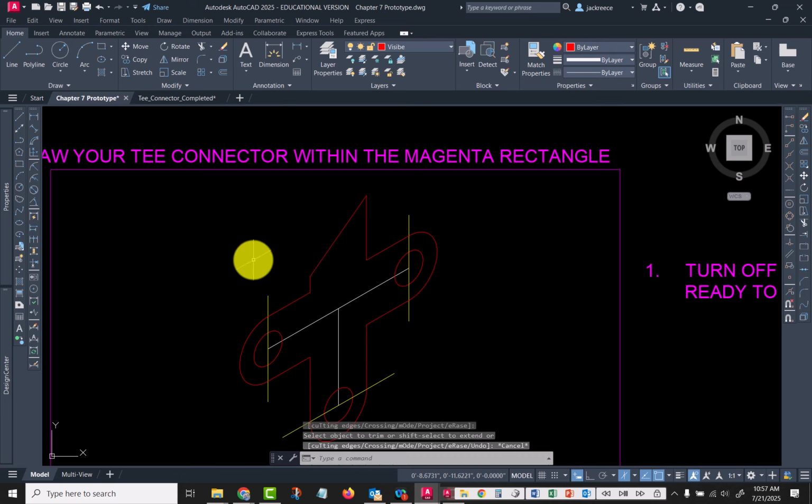Okay, so anytime you're dealing with an angled line from an orthographic view into an isometric view, you've got to locate the two endpoints of that line. Think of it as an X, Y, distance, and coordinate. And so when we drew our orthographic view, here we had an X distance between them here, and then we needed a Y distance here and a Y distance here. And so we drew that in our orthographic view, and it just transferred that information over to here. Okay. We got that. All right.